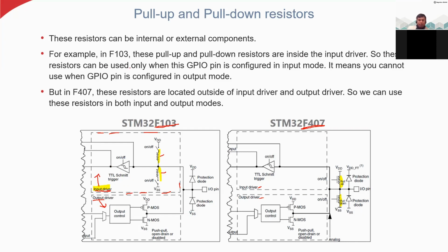So these resistors can be used only when the GPIO pin is configured in input mode. You cannot use them when the GPIO pin is configured in output mode.